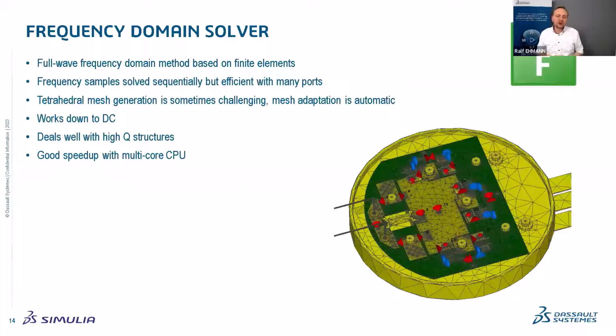So if we would like to simulate the inverter, we move to a full wave method, as I mentioned, and there's a number of full wave methods already in the CST Studio. But for the inverter particularly, we use the finite element method in the frequency domain. This uses a tetrahedral mesh, as you can see down on the right-hand side, and it works down to very low frequencies. You can basically solve at 1 Hertz. There's no problem, and extract the right resistances. Overall, the frequency domain solver scales very nicely with multi-core CPUs if you would like to increase the simulation speed. So that's how the frequency domain solver is applied.